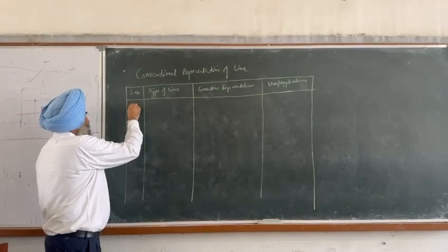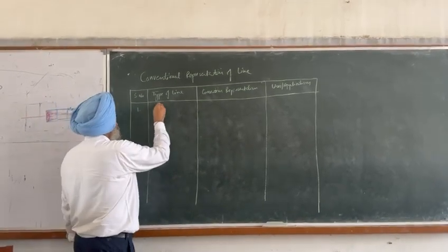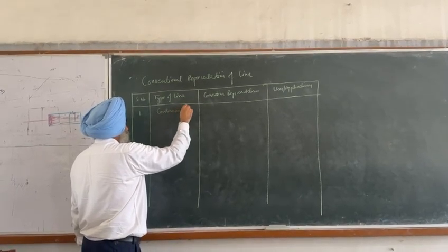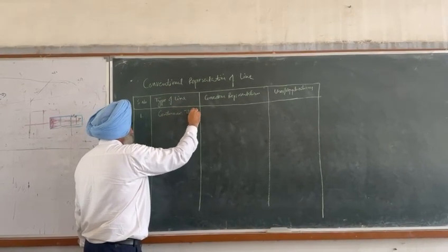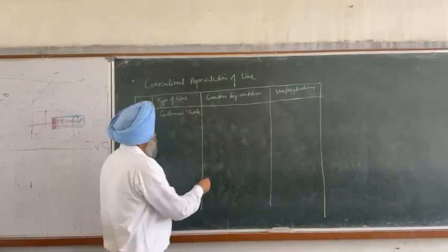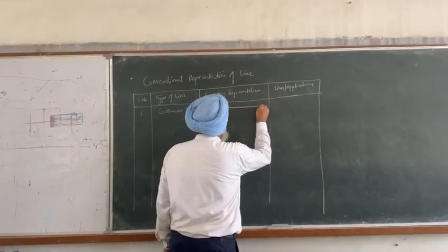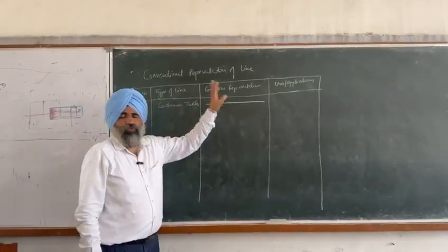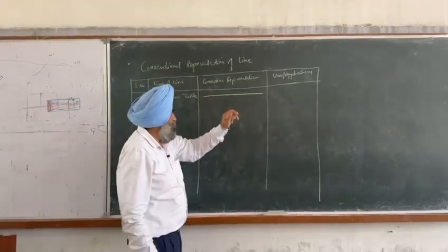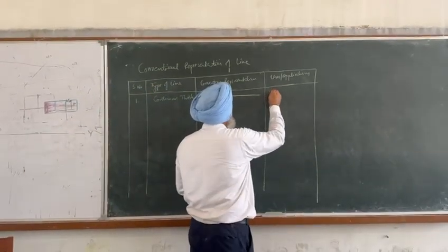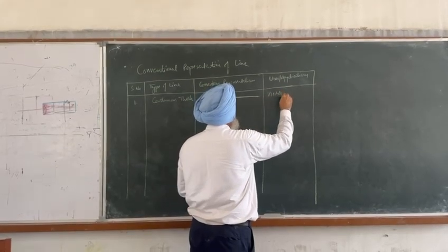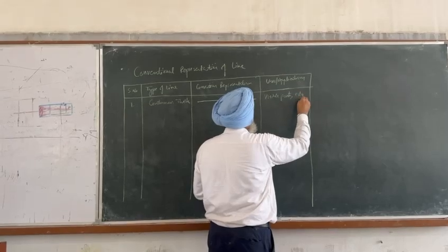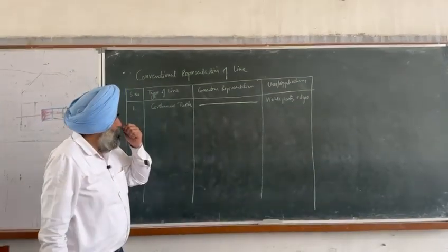The number one is continuous thick. If you are having two types of pencil, HB and H, please make it with the HB pencil. Visible parts, this is the application, visible parts or visible edges.